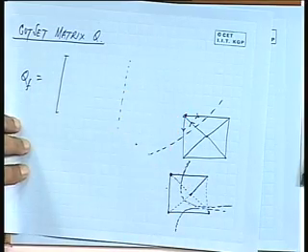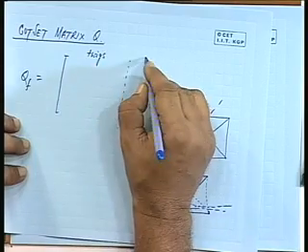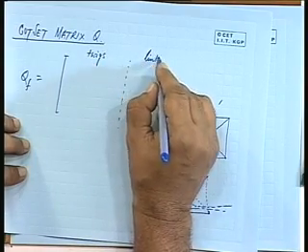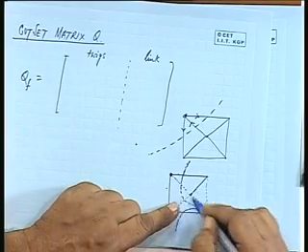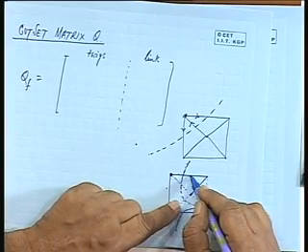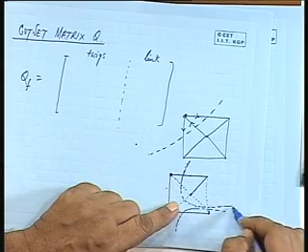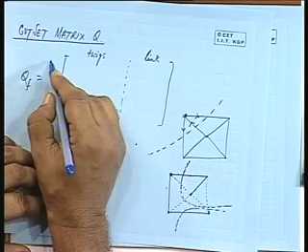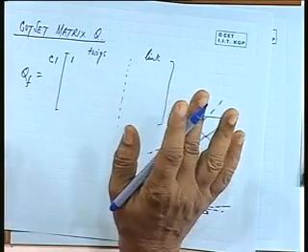what will you observe? Suppose we take twigs, the tree elements, on this side and link elements on this side. I can number them accordingly. First tree element, when it is being cut, this is cut set number 1. So, cut set 1 will have 1 here, no other twig will be cut.